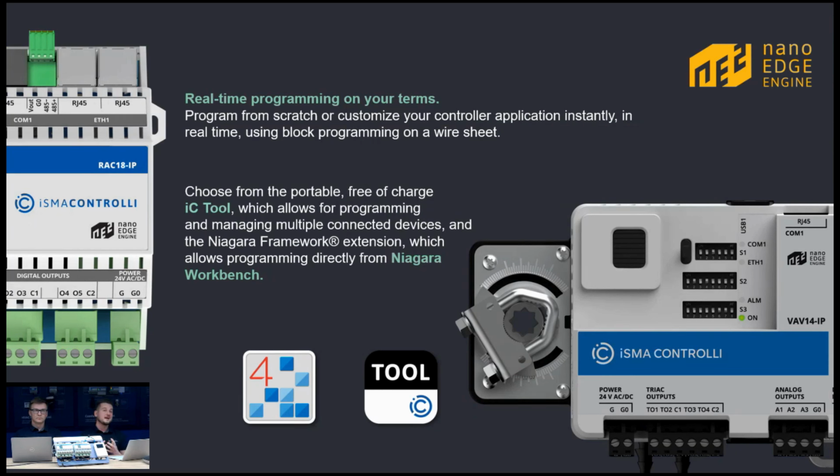But at the same time, we created a special Niagara framework extension for our controllers that will allow not only to integrate the devices in Niagara framework, for that we will use Modbus or BACnet, but will also give you the capability of configuration of the controller with the IP address, backups, application creation using the Niagara wiresheet, and of course, the whole commissioning process and integration. So this is what we have for you.